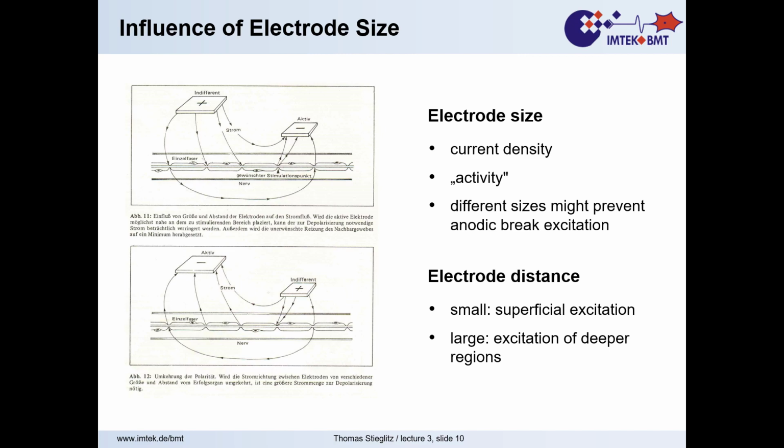If you equally distribute those field lines over the surface of the electrodes, you see that the field line density on the smaller electrode is higher than on the larger electrode. And if it helps, you can transfer that to charge. If we would deliver current, let's say 100 charge particles, then they sit closer together at a smaller electrode than they sit on a larger electrode.